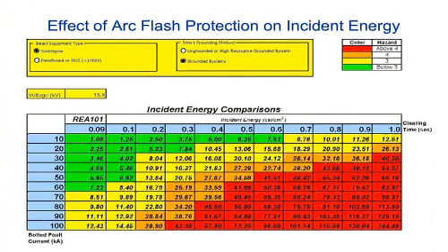What does a 53 millisecond clearing time really mean? As you can see, this green area is defining what the calorie counts are, okay? This tells you just how bad things are. That's why in the red zone, this thing cuts over at 40 calories per centimeter squared, which tells you that you have to shut the switchgear down in order to work on it. The green zone says you're in PPE 1, which is pretty light stuff. You can actually work in that.